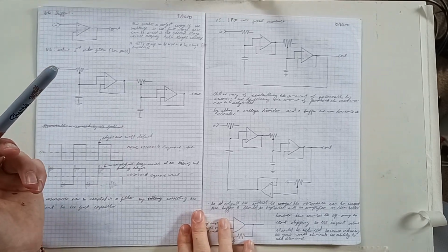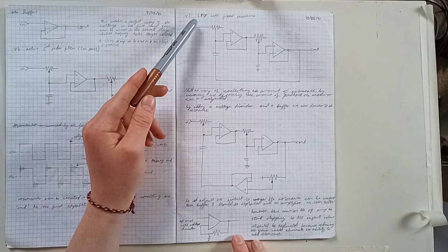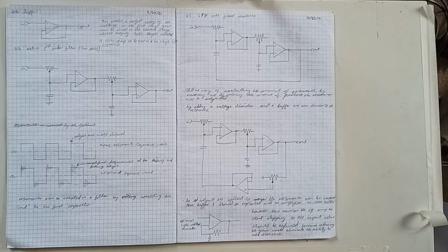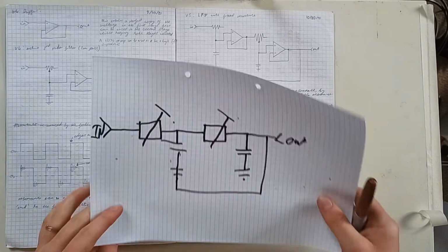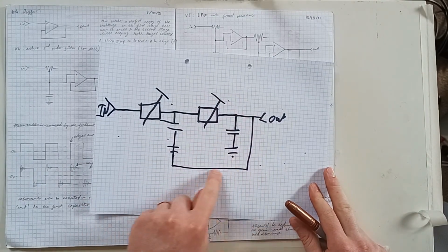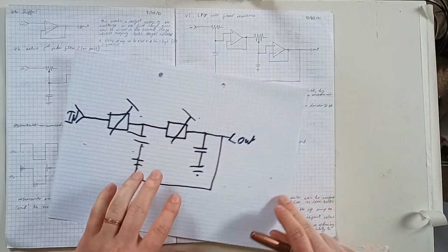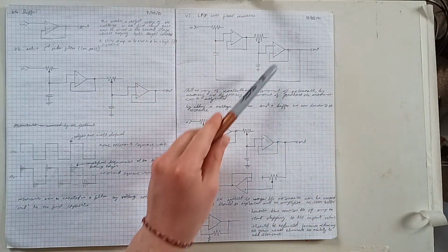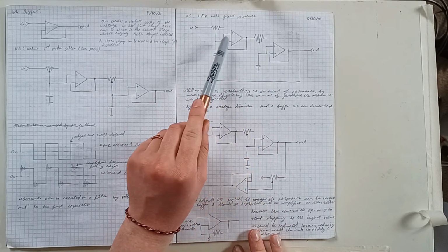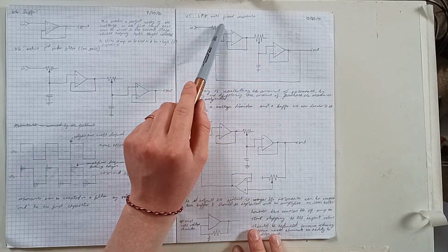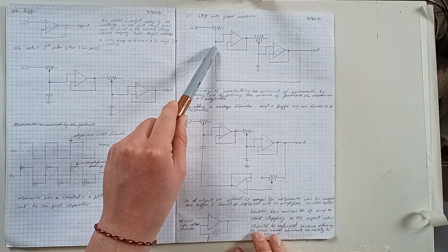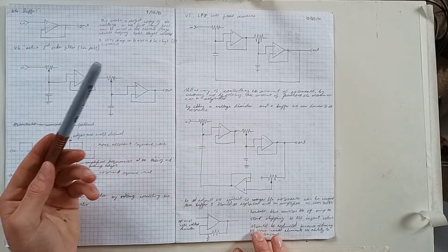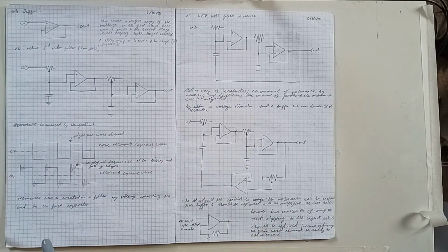So the way you would add resonance is, as I sketched out earlier on here, you connect your output back to the first capacitor, which is what I have shown here, but with 2 buffers in between the output of each filter, so you can see it then goes all the way back to the first filter. And that would give you your amplification around the cutoff point.